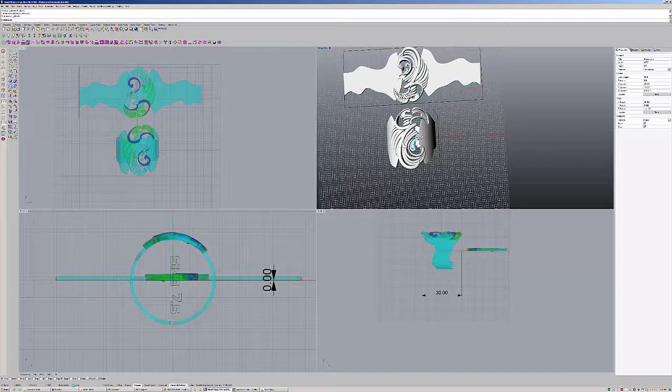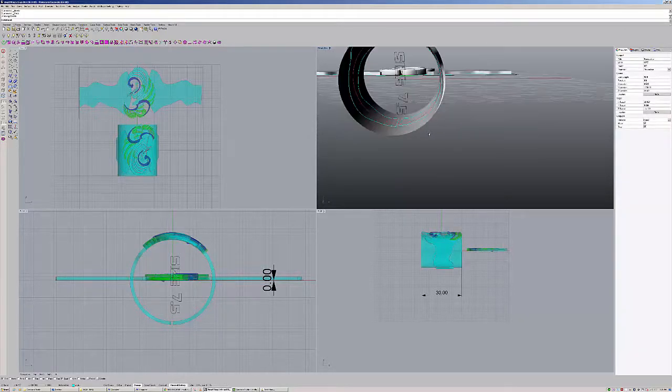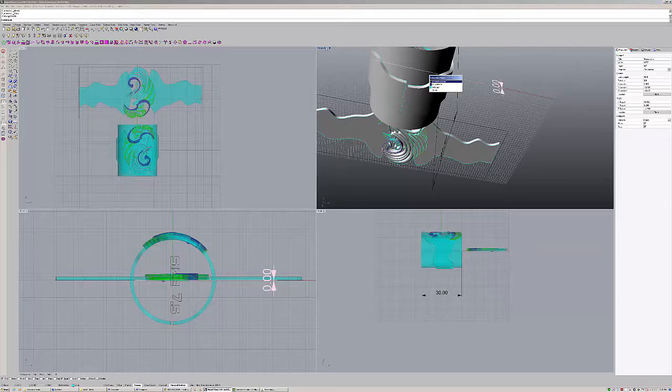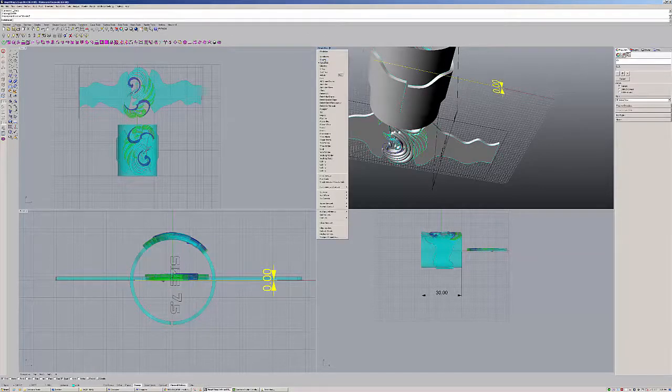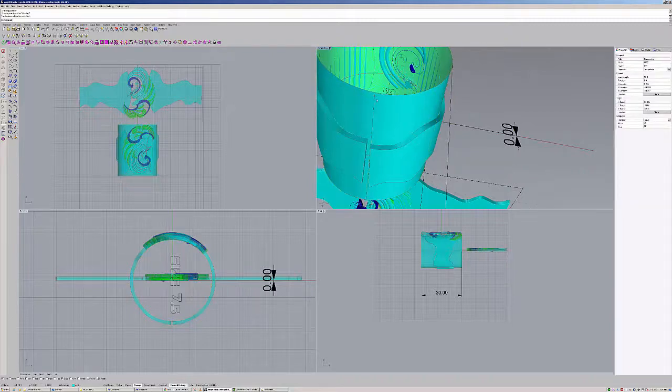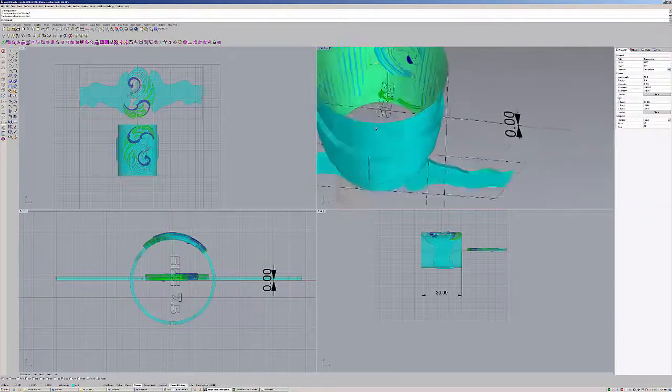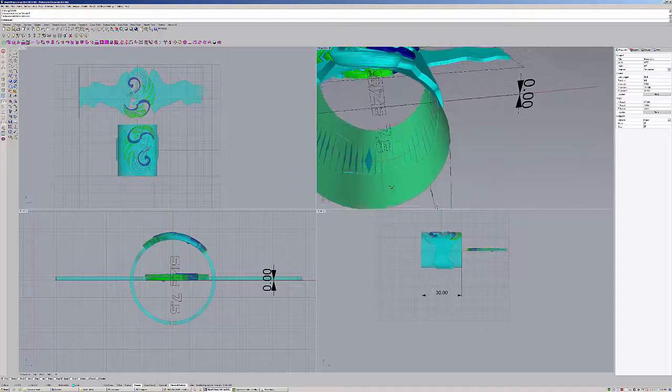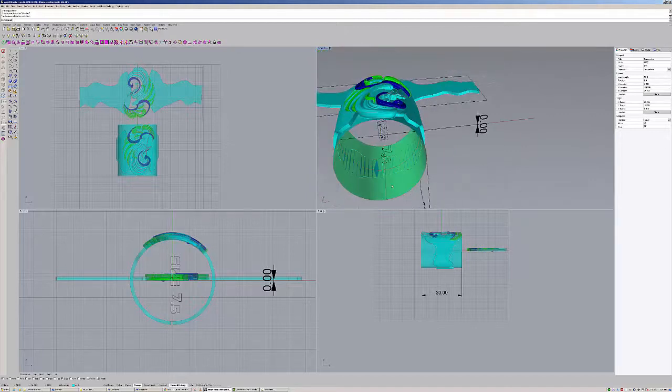So this is basically the seam, okay? I was explaining about the seam of the cylinder. If you look on the cylinder, when I go into shaded view, you see a visible line here. That's the seam. Basically, imagine this splitting, opening up like this, and then laying it flat.